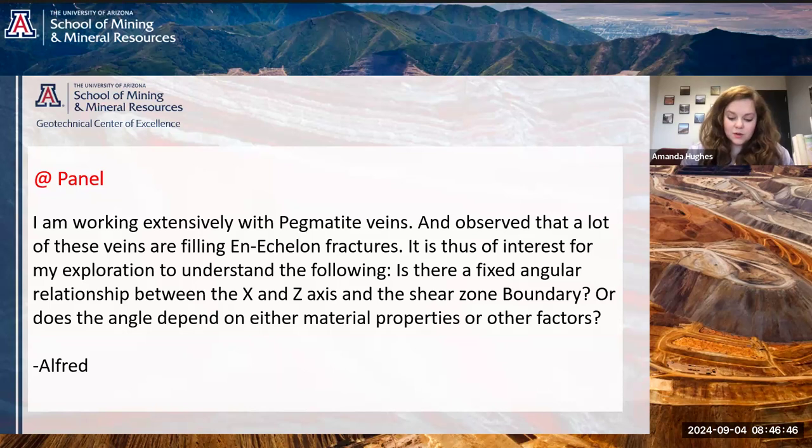But we know from engineering standpoints that when you're in low differential stress, that conjugate shear angle can become narrower. And so it's possible that you would have a narrower conjugate angle for the overall trend, and then your en echelon features are going to sit within that overall trend. So that can change a little bit, but you should see a systematic orientation for your particular set.